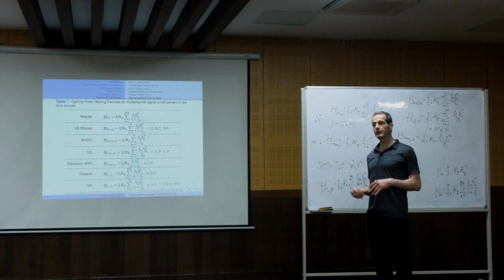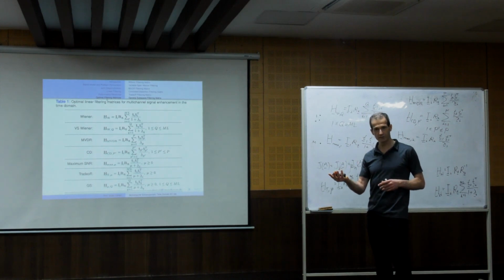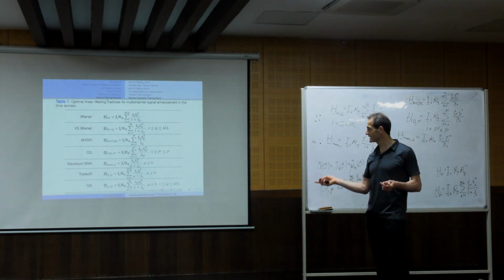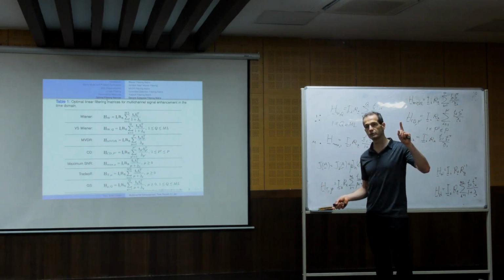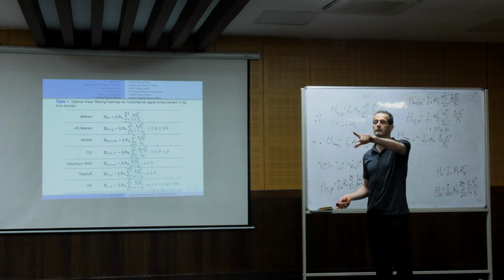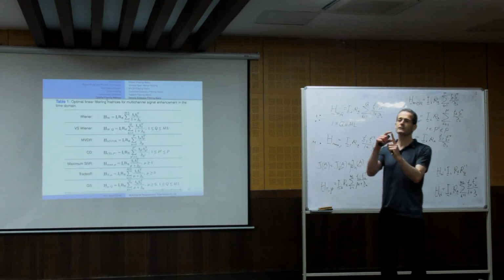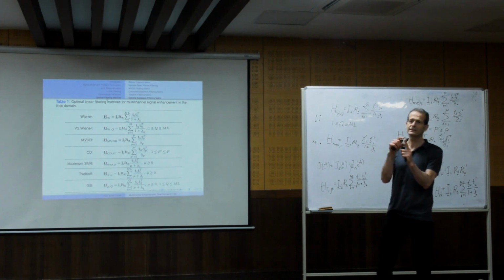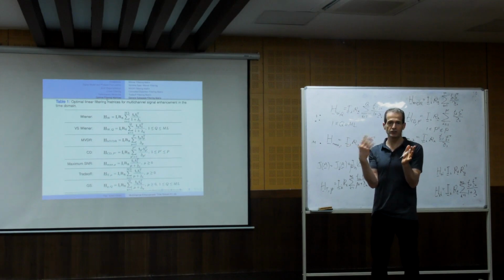Intuitively, think about it: we have many signal components in the signal plus noise subspace. With the maximum SNR filtering, we keep only one component. Which component do we choose? The one with the maximum SNR, exactly. So we keep that one. Now, if we multiply this component with a certain value, do we change the output SNR? No. We don't change the output SNR.